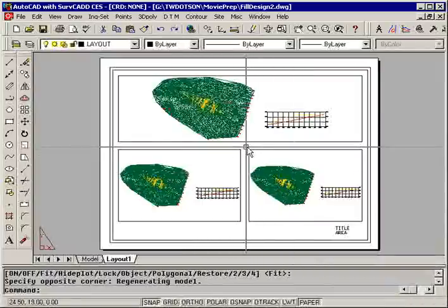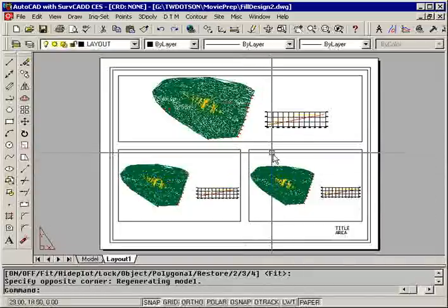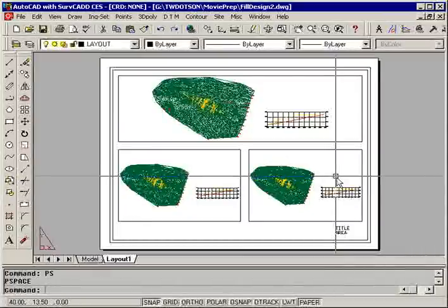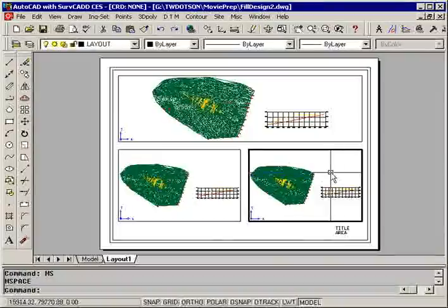We are currently in paper space within the paper space environment. We can switch to model space and work inside viewports. There are several ways to do this. There are toggles and so forth, but for now we'll just introduce the aliases of MS and PS. MS for model space. When I type MS and hit enter, you'll notice that my cursor is chopped off and I have fallen into one of my creative viewports. I can type PS to return to paper space to achieve a full crosshair.